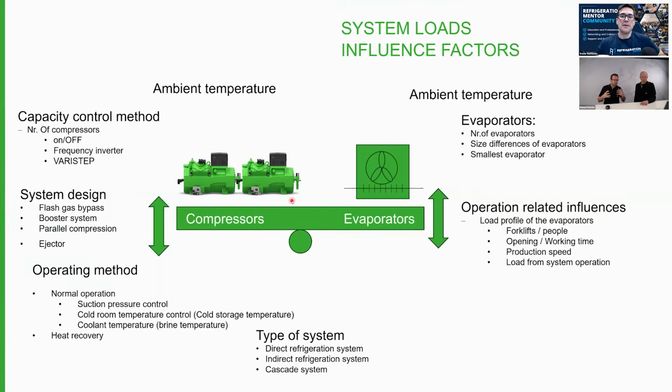but it's also bringing, let's say, the scale into a movement. Parallel compression, then we basically have to see it as 2 scales. So the MT compressor has its own scale and the parallel compressor has its own scale. Of course, the influencing is always a little bit the evaporator load plus the ambient, for example. So trying to have both scales balanced is the challenge.